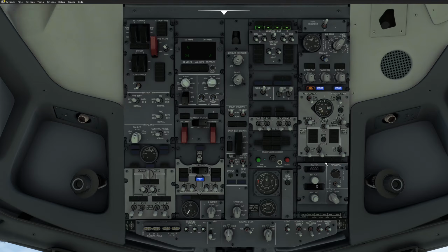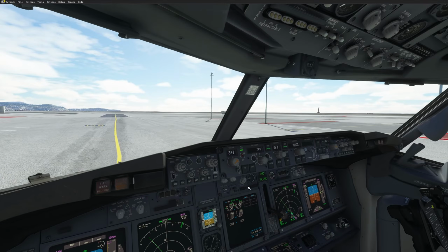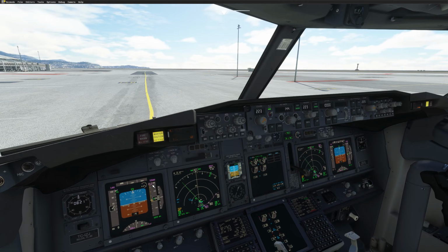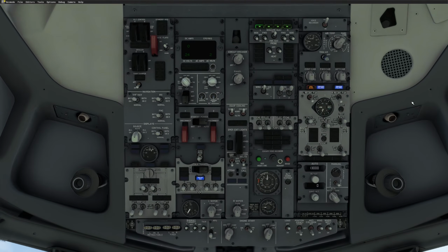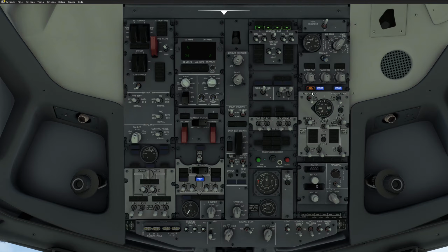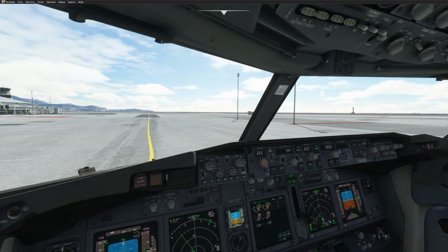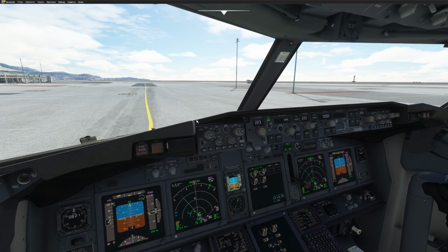If I forget the APU, for example here, and I continue my flow, I'll go to the engine start switches to continuous. And now what we do when we have done the flow, we press recall. And now you see there is a light, and the light is air conditioning. So that tells you if you forgot something. And then you find out the light is dual bleed, and you know that you forgot to turn off the APU. Very nice. So once this is done, recall is checked.